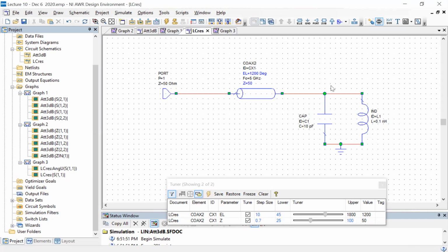And the calibration procedure, which I just briefly explained to you, requires replacing this device with known objects, so that you can say, okay, this is an open, this is a load, this is a short, or something else. And that, of course, is very challenging. How will I do this when this object is inside a fridge?